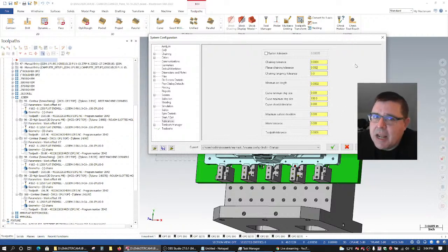regular parts. If you're bringing in something the size of a ship or an airplane, something completely giant, you may have to go up here and set your tolerance to kind of 1/10 of a millimeter, 1/1000th of an inch instead of millionths, because the size of the object that you're bringing in is just so large, and it's hard to deal with it computationally when your tolerances are cranked way, way down.